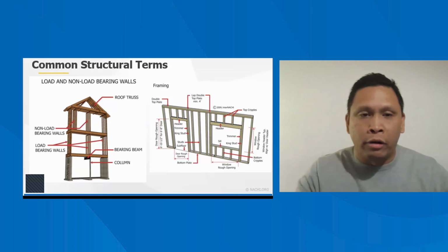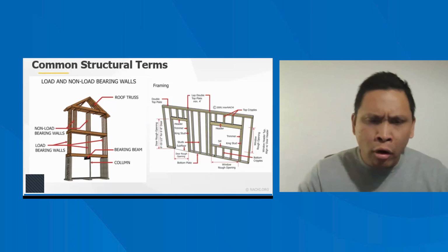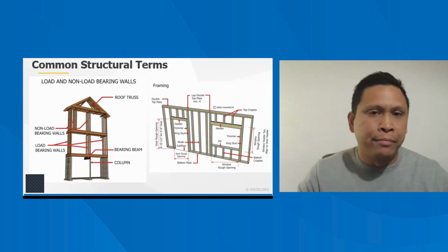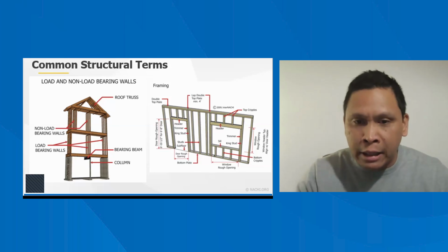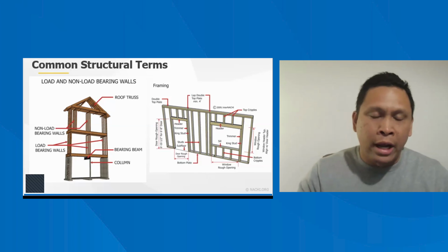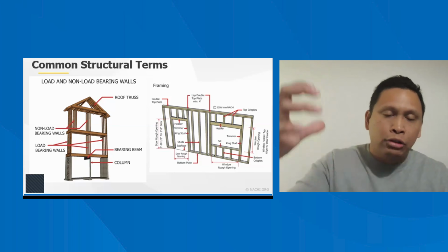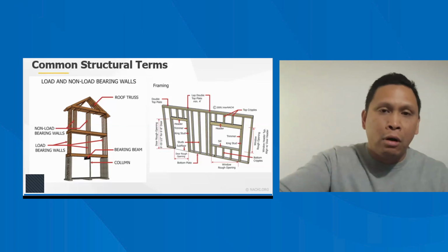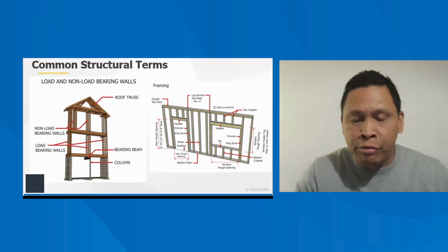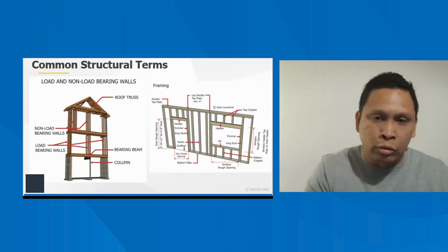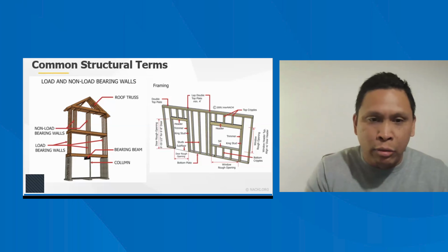So oftentimes when we're going through homes, more of the modern day homes, we'll see a support post, right? Metal support post known as a lally column. So it's going to help transfer that load from up above all the way down, and then into the ground, and then through the footer, which is what we call a continuous load path.